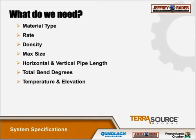Temperature and elevation are very important. It's going to affect the air density. As an example, air at 2,000 feet is going to be 7% thinner than at sea level, and air at 100 degrees Fahrenheit is about 5% thinner than at 70 degrees Fahrenheit. If you don't take this into account, your system might operate in the morning, but then not in the afternoon when it heats up. So at Jefferator, we always make sure that that is accounted for.